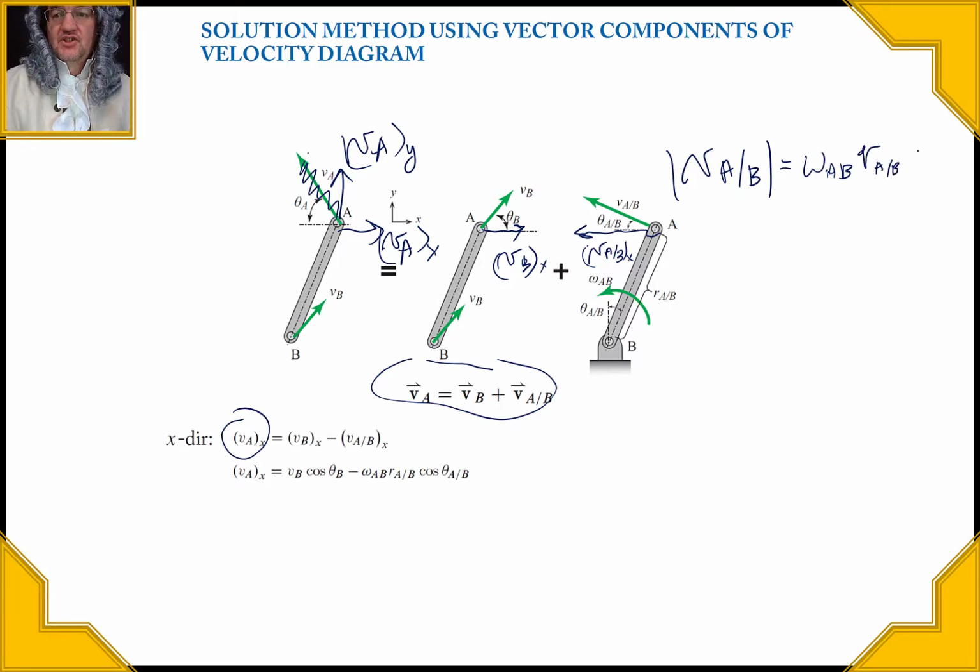But a lot of times we will just replace that with whatever the length of the thing was, so maybe I would write just L_AB. That's the magnitude of the thing. And then I would multiply it by the cosine of this little angle that's inside there. And I would know that angle quite often because I would know what this angle was right there. I would know that it would be the same onto the thing.